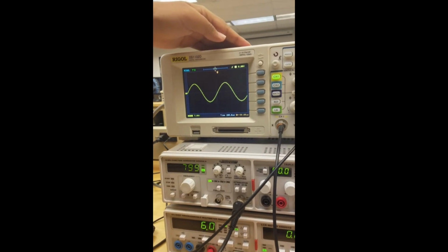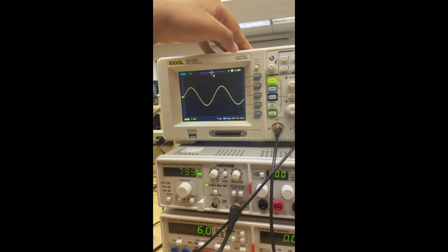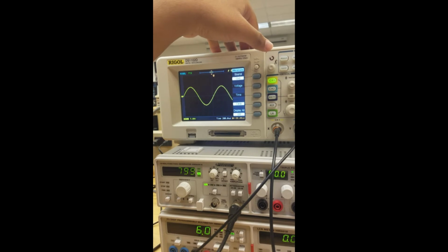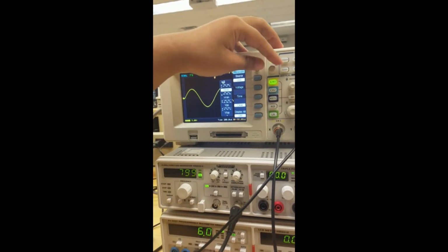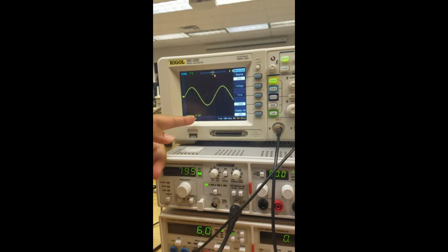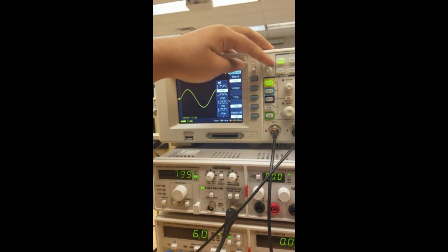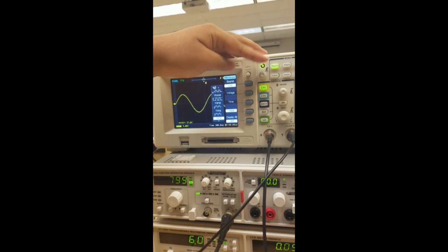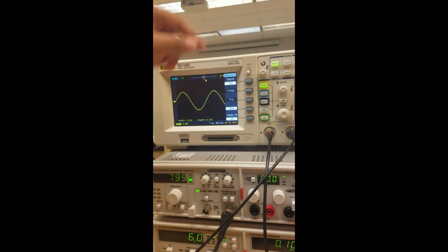You want to press buttons on the digital oscilloscope. So to measure volts peak to peak, you want to go to measure. Would be for channel 1, by the way. So for channel 1, go to voltage, then go to VPP, click on the button, and you get 17.6 volts for the peak to peak for channel 1. You do the same thing for RMS too here. You get 6.21 volts for the VRMS.